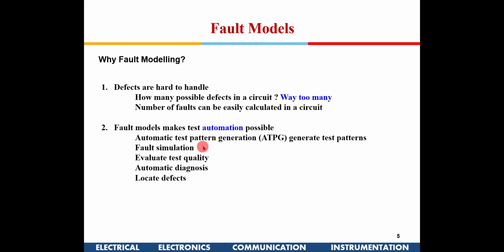Fault simulation is possible. That means you have made a circuit, you have written a Verilog code, and now you want to simulate some fault. Say at a point you want to see if this particular node gets stuck to ground, what would be the effect on the circuit. Can you do that simulation? You just have to write a code accordingly, so that at that particular node it is stuck at 0 or stuck at 1. So you can simulate that fault easily. And then you can give an input signal and try to see how to detect that.